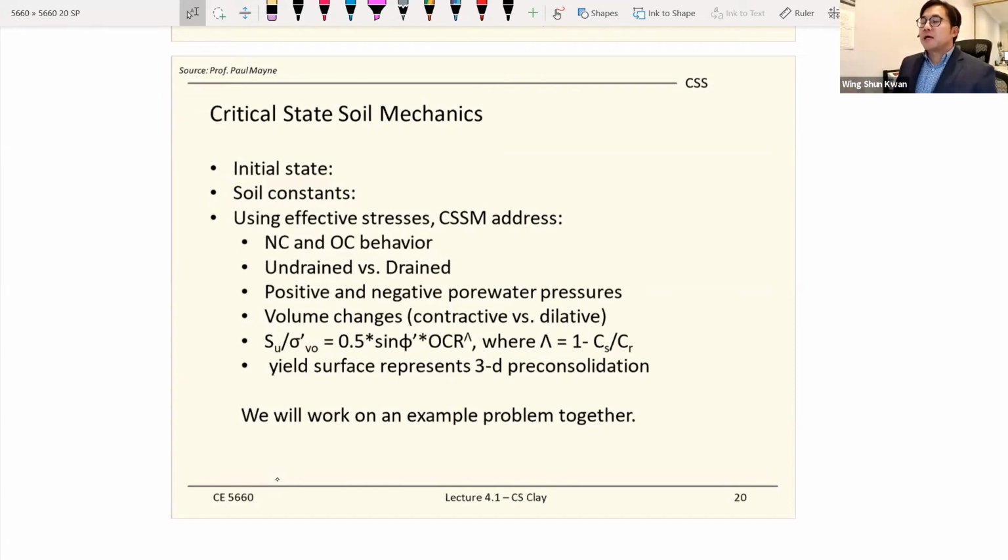And the slopes are the soil parameters, just like we learned in the 366 geotechnical engineering course at the undergrad level. We talk about the compression index, the recompression index, and the tangent phi, which is the tangent of the friction angle, giving you the failure envelopes. Those are the slopes that you need. A point, a slope, then you can form the lines.